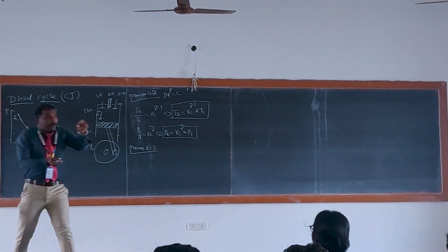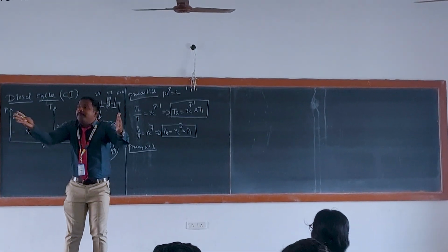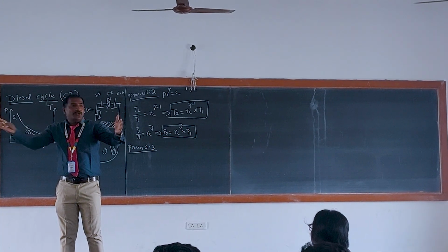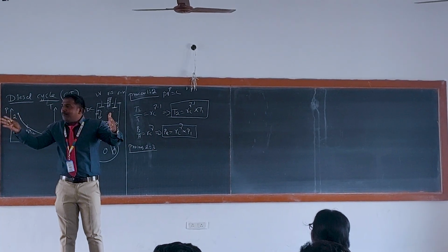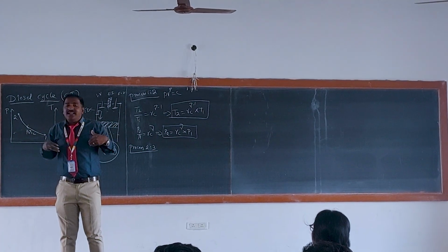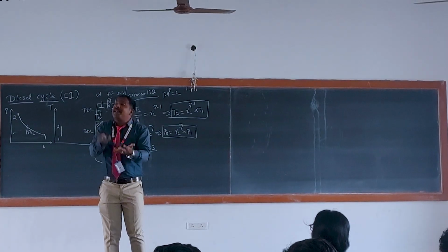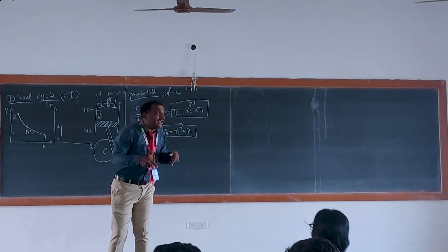So fuel injection takes place for a period of time. Due to this period of time, what do we take? We consider there is a constant pressure heat addition, because whatever rise in pressure, that is adjusted by the movement of the piston.